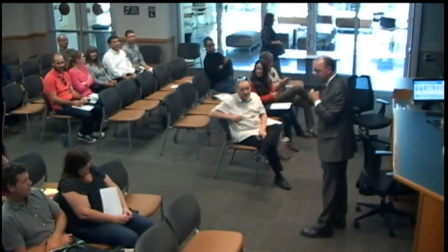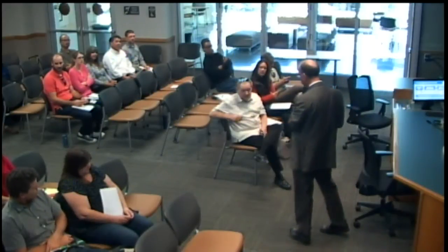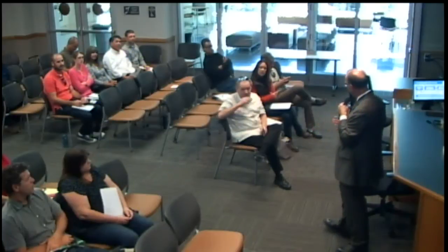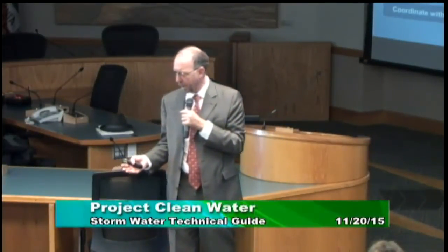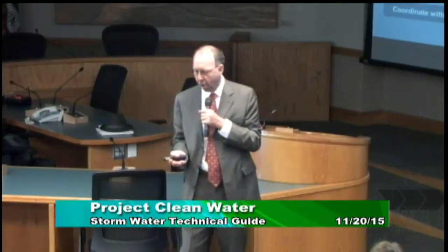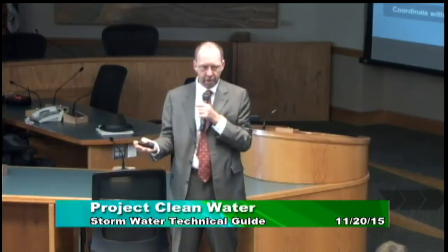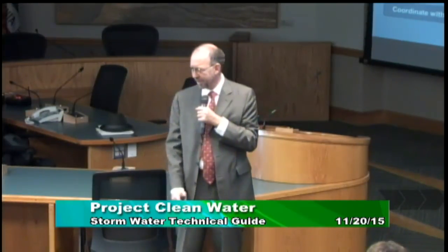I'm going to answer your question in the generic sense from working around the state, and then I'll see whether anybody from an agency wants to respond. The reason is that often the critical point that makes the difference in whether you end up with a good design that benefits the community and saves the developer money is before the lot lines are drawn, before the building footprints are decided. Once you have set those things, and then you move downstream and say, okay, we're going to approve that the way it is before the planning commission, and then we're going to do the drainage design later, with LID you often end up in a situation where you approved a site plan with plenty of green space on it. Too bad all the green space is 3 feet higher than any of your impervious surfaces, and I've seen that happen.